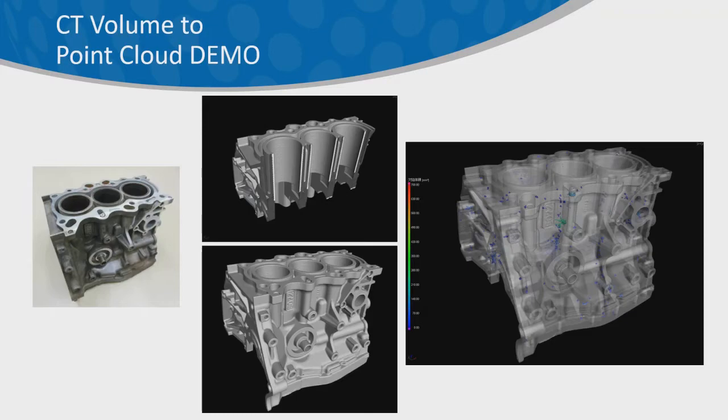And again, another example of looking at a small cylinder head here. So taking the head, scanning it, thresholding the data, capturing the surface data, and then one example you see here as well is we can also quantify defects. So in castings and additive, if there are embedded porosity defects, we can go through, segment those, and really quantify them as well, so we can get statistics about their size, morphology, and things like that. So it becomes a really, really powerful tool in castings and additive manufacturing.